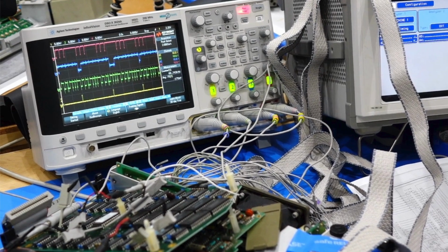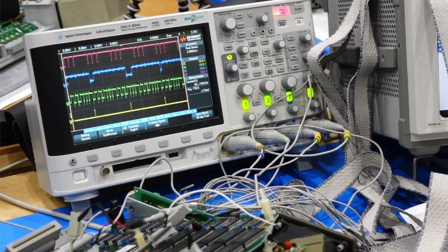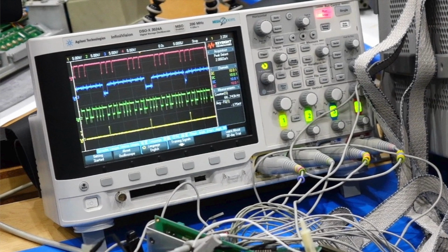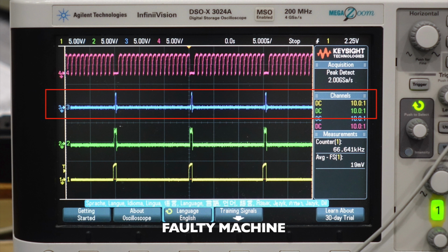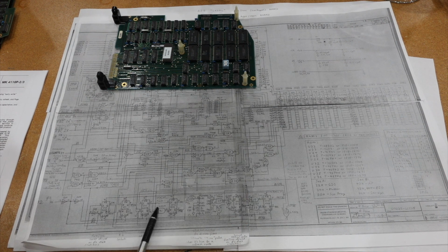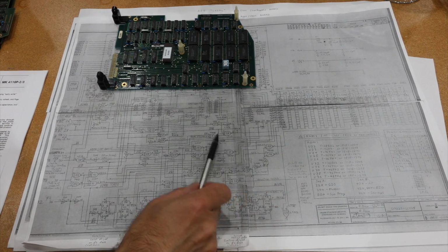In particular, pay attention to the blue count signal, the one that advances the refresh counter. They look nothing like each other. One is mostly high with short low periods of various length, while the other is mostly low with very short, even length high pulses. We were pretty sure we'd soon find a big bad faulty gate in the noodle logic,